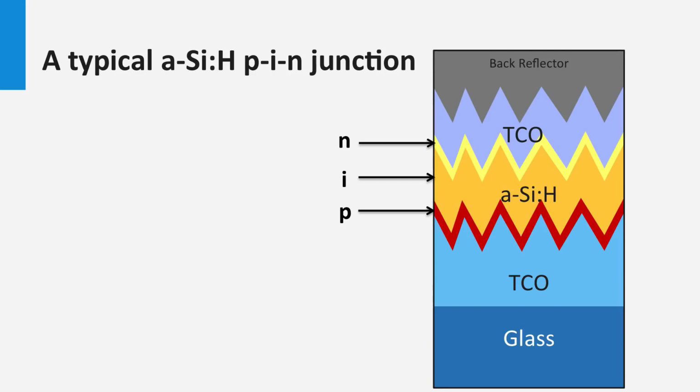Typical TCO layers are fluorine-doped tin oxide, aluminum-doped zinc oxide, boron-doped zinc oxide, hydrogen-doped indium oxide, and ITO, which is tin-doped indium oxide. These films are processed using either sputtering, low-pressure chemical vapor deposition, metal organic chemical vapor deposition, or atmospheric pressure chemical vapor deposition.